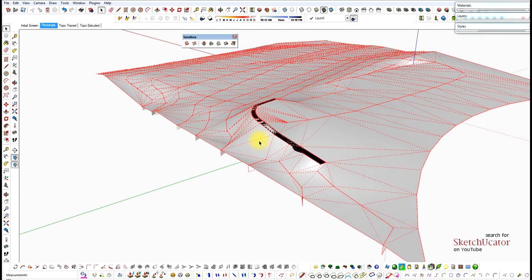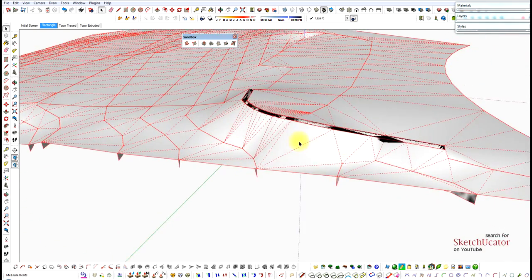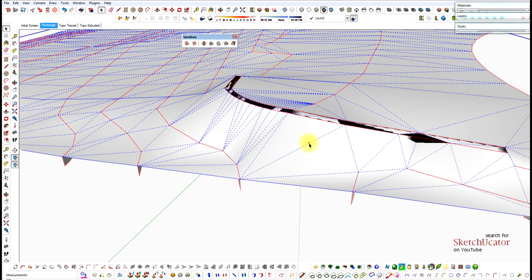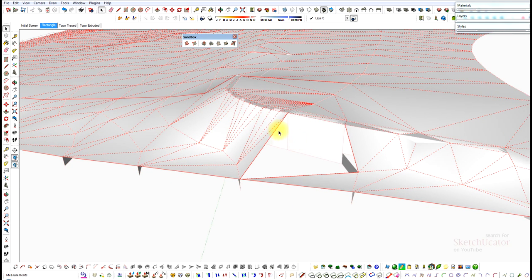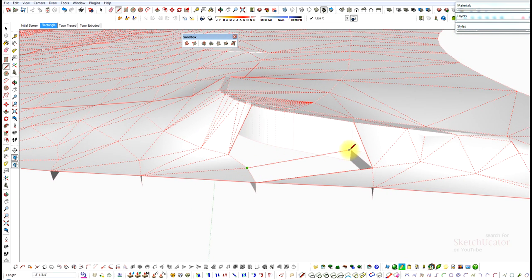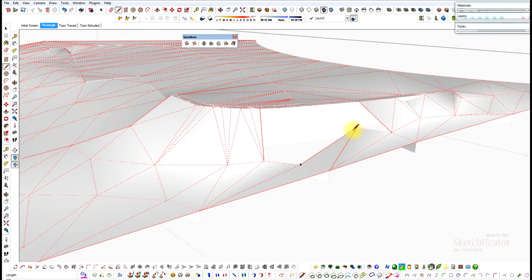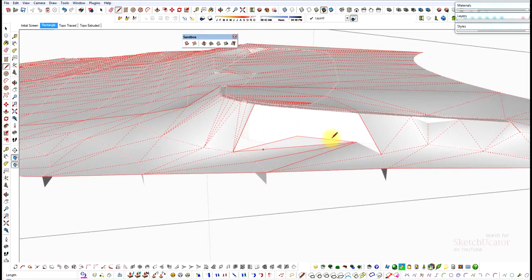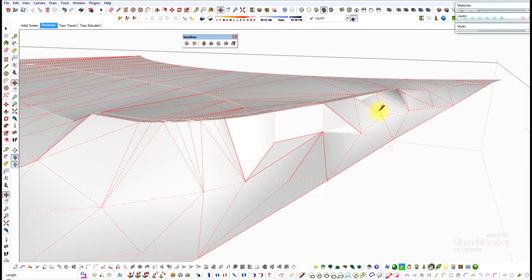You can see the retaining wall is a little goofy because it's tried to interpolate that information. If you need to at some point and you want to clarify this, you could eliminate these faces and potentially come back in and add some faces. You need to make triangles to do this. So you can see what I'm doing is I'm reshaping the topography here. Triangles would be necessary. Now I'm not going to redo that whole thing, but you see what you can do.